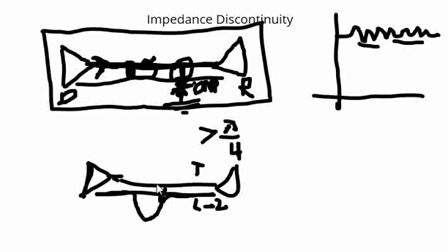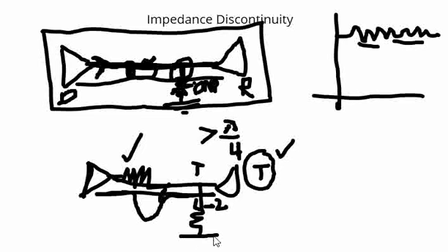Another important parameter is the terminations that will be done in high-speed designs. You can look at our videos in our channel to understand the terminations, and there are many resources available over the internet. We will have source termination, which will be done near the driver, and a parallel termination, which will be done at the receiver side. If these resistors are used without careful consideration of what the driver impedance is and what the line impedance is, this might cause unnecessary impedance discontinuity and reflections.